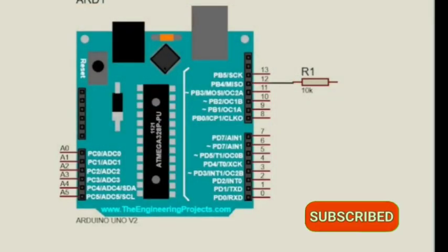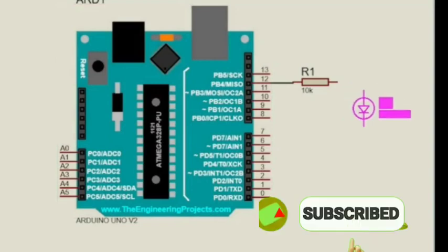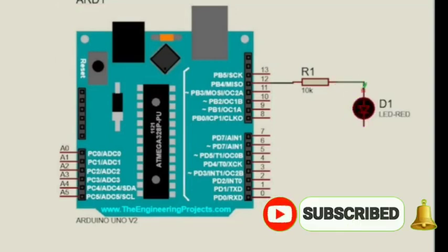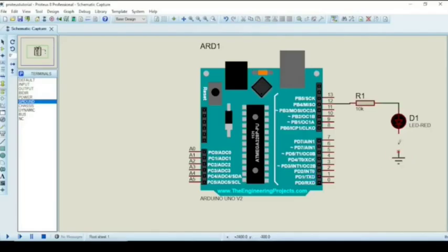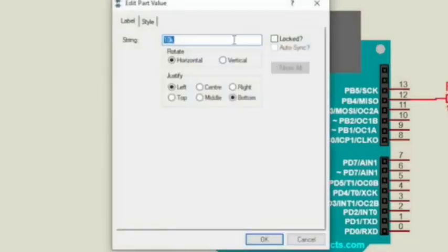The resistor is 10 kilo ohms by default. This is a very high value. This may make the LED brightness very low, so we can use a 0.22 kilo ohm resistor. This limits the current to an appropriate value. To arrive at this number, you can use Ohm's law. We have made the Proteus hardware connection.